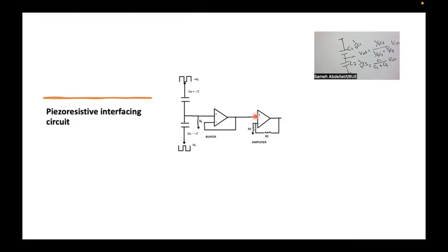So you can see this circuit as three cascaded units. First, we have these potential dividers using the two series-connected capacitors. And don't forget that we impose this pulsive signal in order to ensure an alternating voltage compatible with the nature of the capacitors. And then we have a buffer, and finally we have the non-inverting gaining unit in order to ensure a reasonable gain of our system.